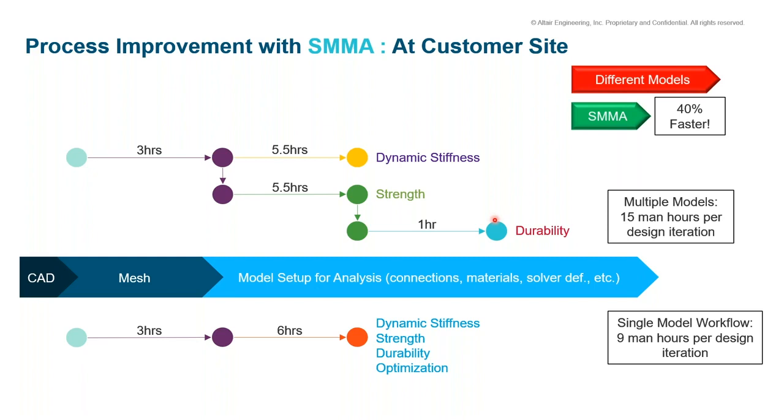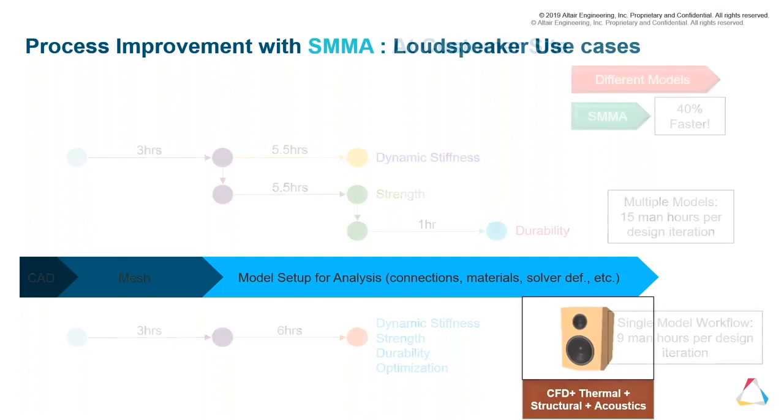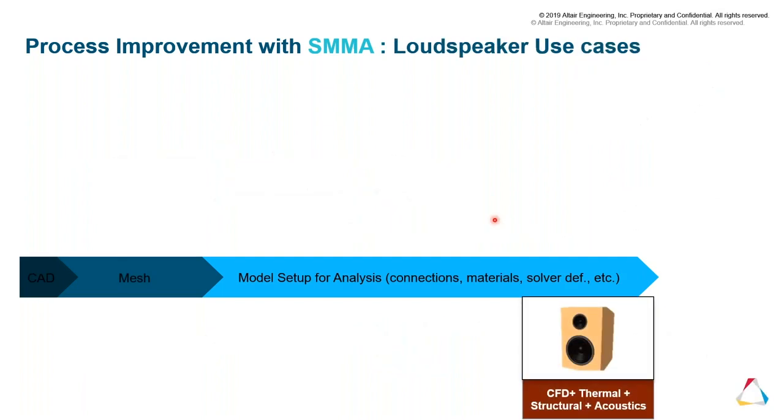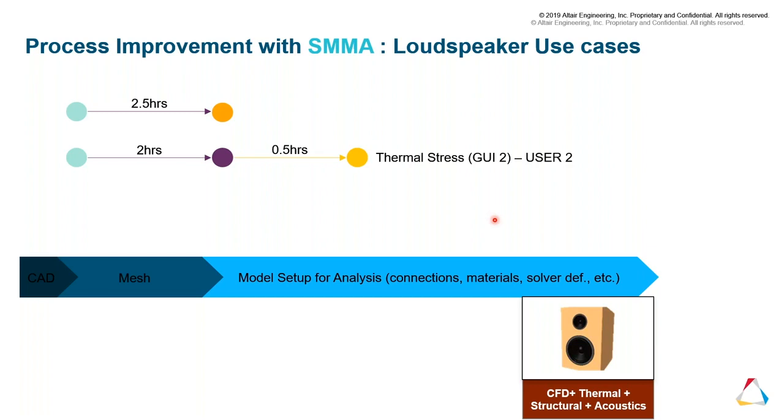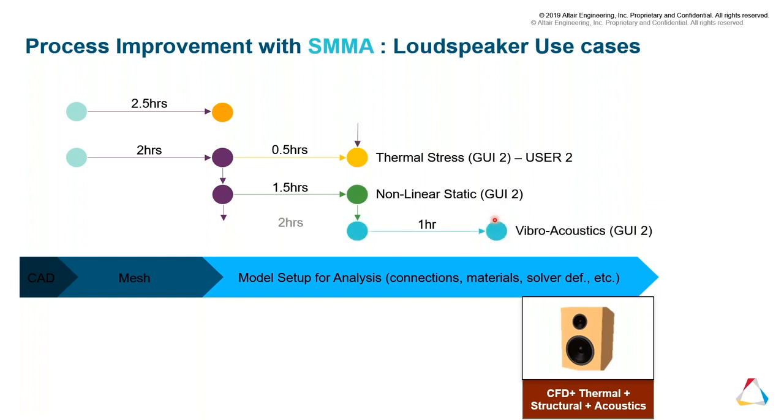I don't think there is a tool out there which can solve multiple solutions in a single model, multiple different physics in a single model, the way we do it in OptiStruct. With mapping this same thing with our speaker model, I think that's interesting how we want to look at this with respect to those analyses which I just showed you before. Now, I'm challenging myself here with the CFD, the TFSI analysis. I'm challenging myself here doing a nonlinear analysis, and also the final goal for us to do any kind of acoustic analysis in this particular model.